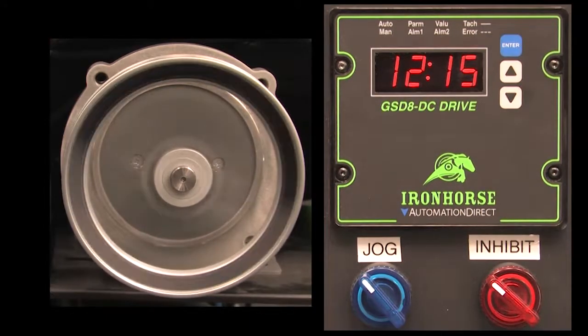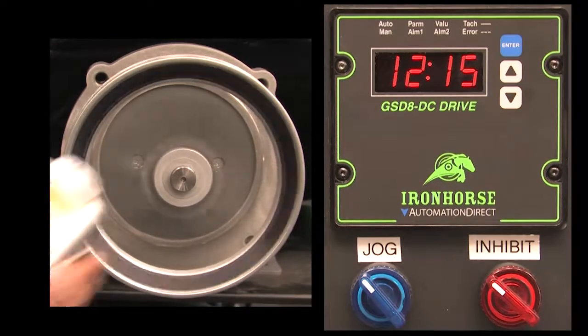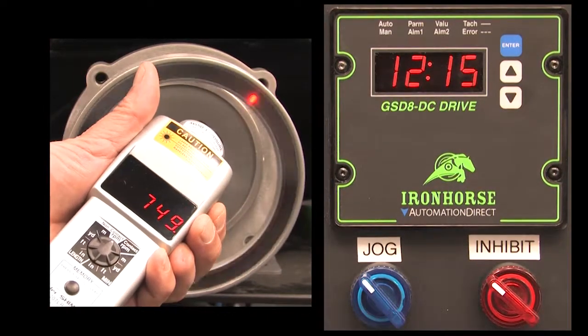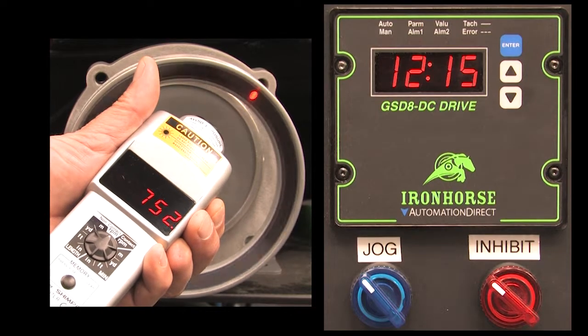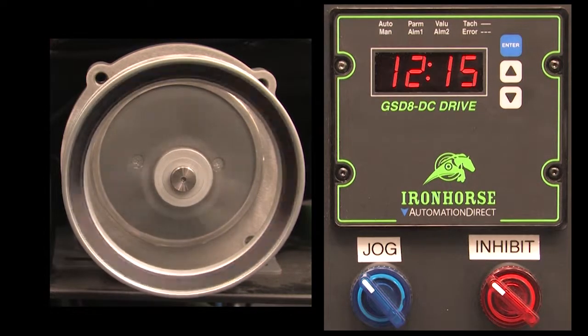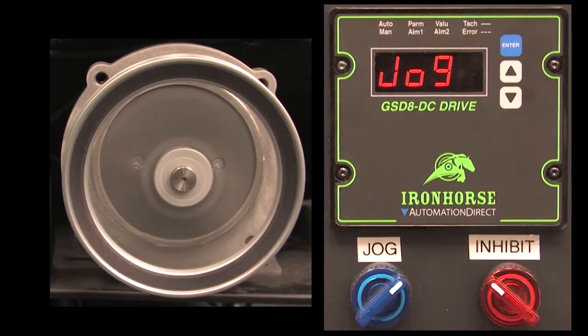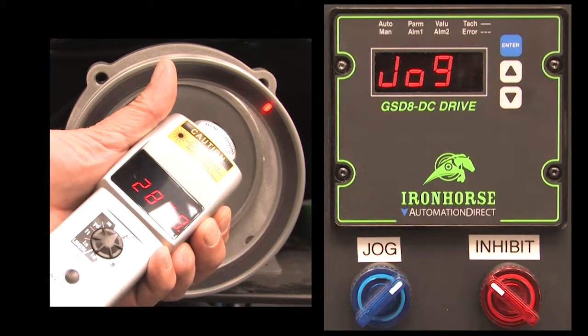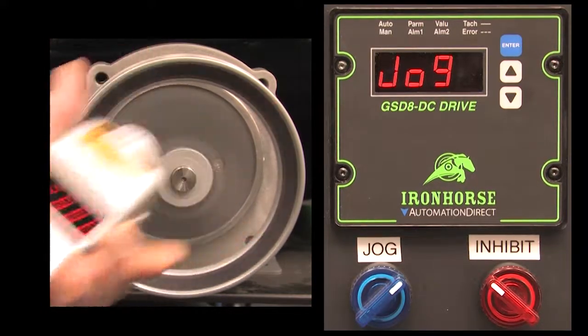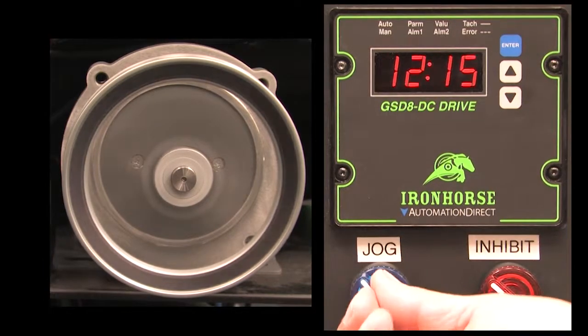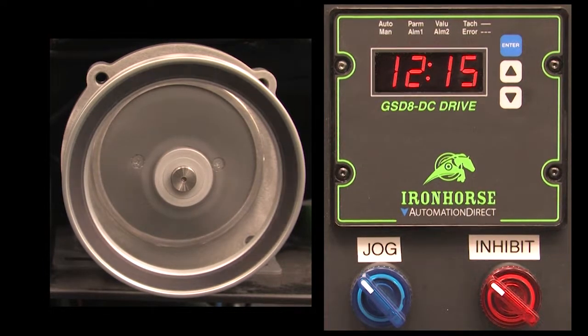And out of curiosity, I wonder what RPM that is. Now, it's a longer duration in the oven, so it should be a lot slower RPM, right? And it is. But how cool is it that we didn't have to figure that out? The drive did it for us automatically. I love this feature. Now finally, we set the jog to expedite the conveyor through the oven in only 2 minutes. So that should be a lot faster RPM, right? And sure enough, it is. And notice that the jog is not limited by the min-max durations we entered. 2 minutes is a lot faster than the 6-minute 30-second limit we entered, isn't it?